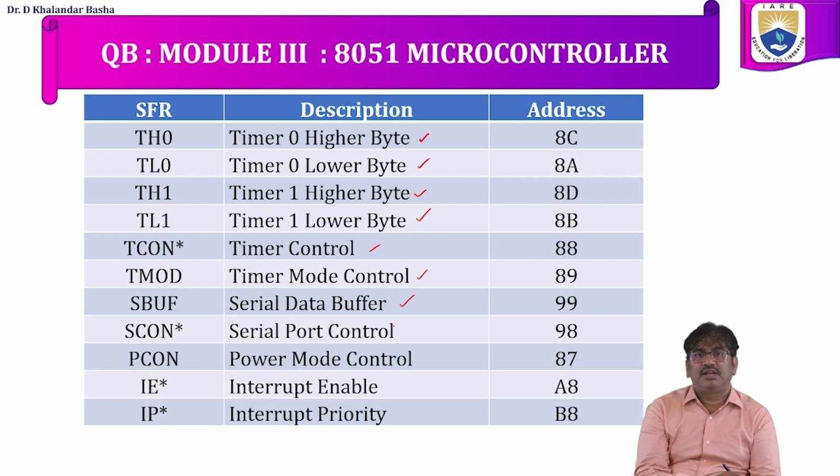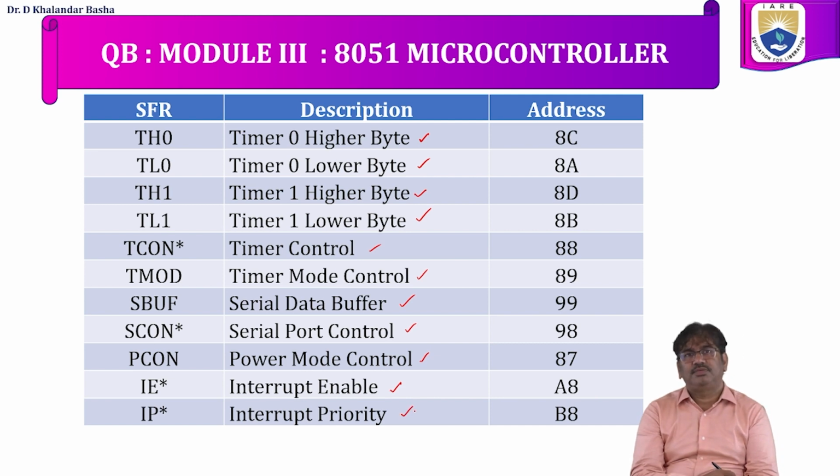SBUF for serial data transfer, the data will be loaded into SBUF. For serial port control, we have SCON register. PCON is for power control. For interrupts, for enabling the interrupt, IE register. For giving the priority, we have IP register.